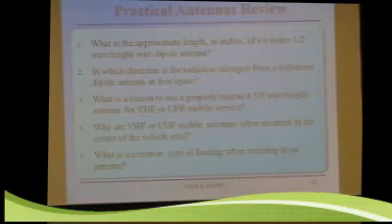What is a common type of loading when referring to an antenna? We touched this briefly. You insert an inductor into the radiating portion of the antenna to make it electrically longer. And again, the inductor will get warm. You don't want it to get warm, but it does. Your antenna is just not as efficient, so that's why you wouldn't use one at home if you can help it. But in a car, you can't have a 60-foot antenna off the back, so you have to use inductors to make them work. Any questions on that?